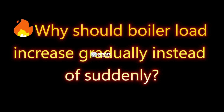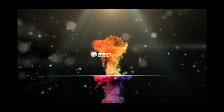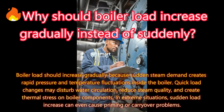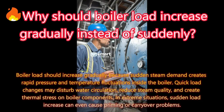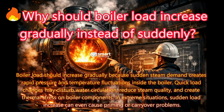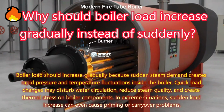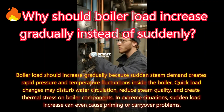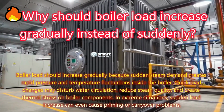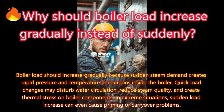Why should boiler load increase gradually instead of suddenly? Answer: boiler load should increase gradually because sudden steam demand creates rapid pressure and temperature fluctuations inside the boiler. Quick load changes may disturb water circulation, reduce steam quality, and create thermal stress on boiler components. In extreme situations, sudden load increase can even cause priming or carryover problems.